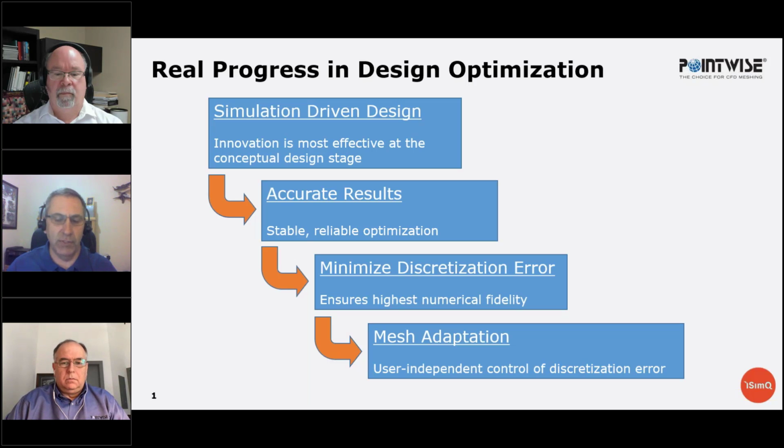So this has a wide variety of implications. One, you have systematic errors, like how well resolved is the geometry with respect to the physical device, the as-built device. Usually we're modeling a simplified design, and that imposes errors on the result, and we want to keep those bounded. Typically today we're addressing those types of errors by including more and more geometry fidelity in our calculations. So we're using fillets on turbo machinery. We're modeling trailing edge treatments on aircraft. We're increasing our geometry fidelity to reduce that error.